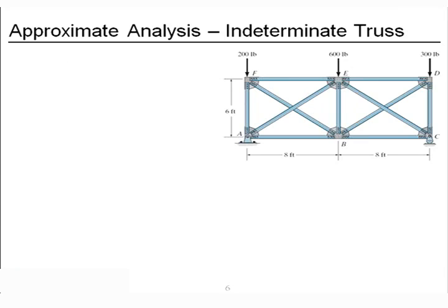Cut our truss right through the first panel. And let's draw a free body of just the left part. I'm going to consider it more like a solid beam so I can get the net internal force at the cut. We have our 500-pound vertical reaction, our 200-pound applied load, our unknown shear at the cut, and our unknown moment at the cut.